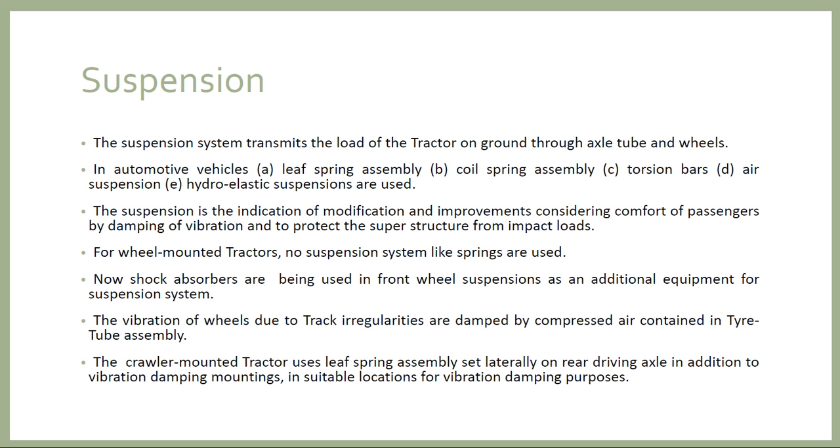But here, in the case of heavy earth moving vehicles, the suspensions from leaf spring assembly to hydroelastic suspension systems indicate modification and improvement for considering the comfort of the passengers by damping of the vibration and to protect the superstructure from the impact loads.